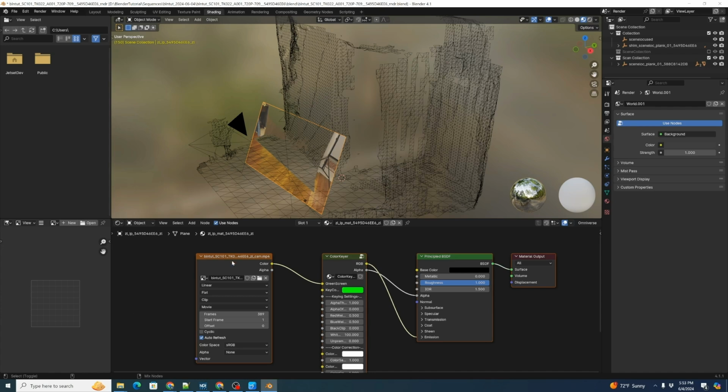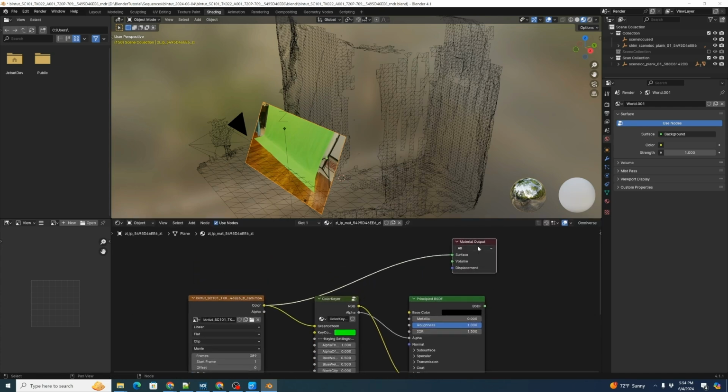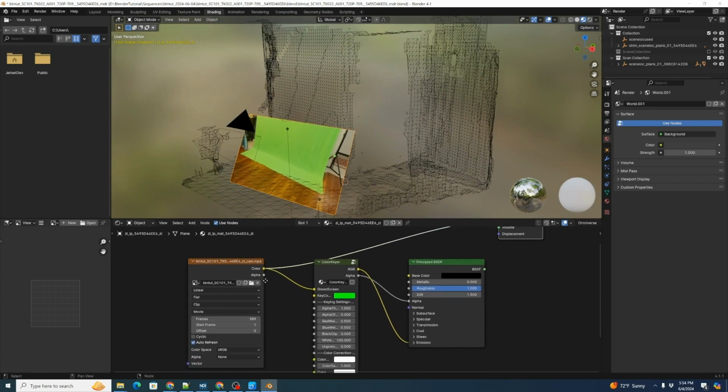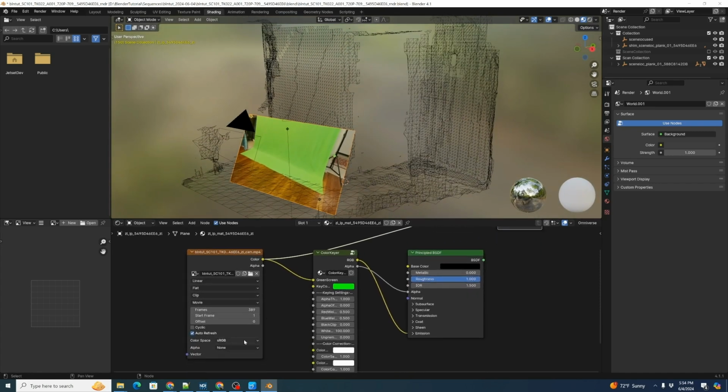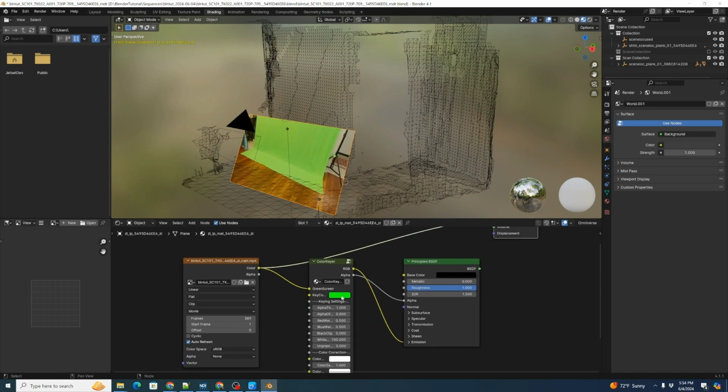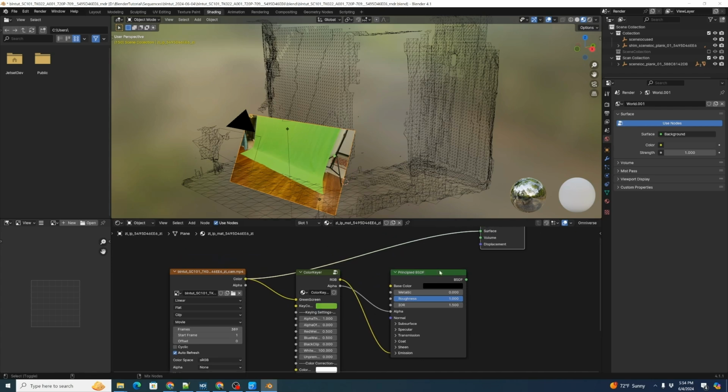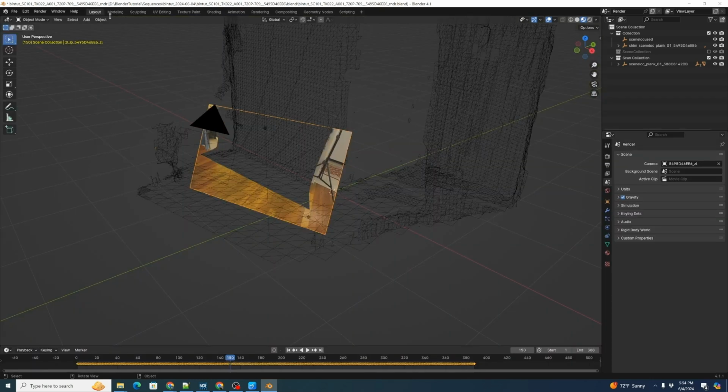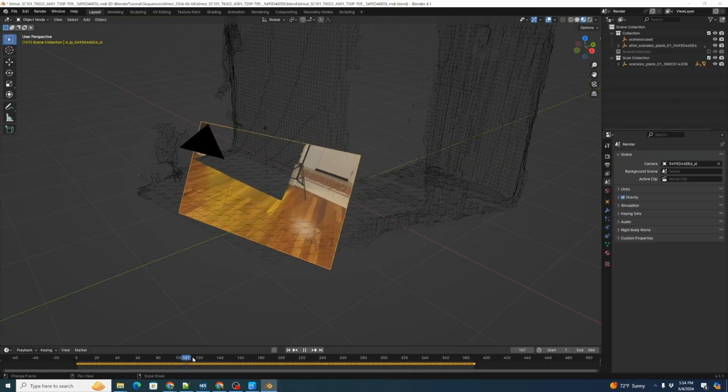So we're going to hold down Shift Control and click onto our Camera Original tab. This runs a wire directly from our Camera Original tab over to our material output so we can see the true color of the image. And we can see here that the color space is an sRGB image, which is correct. And we're going to click our key color, grab our eyedropper, and then click on there. And now we're going to, again, Control Shift click on our principled shader, and voila. So now we have a nice clean key, and we can go back to our layout, and here we have it. Now we can see the keyer working.